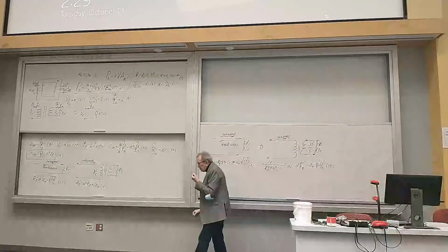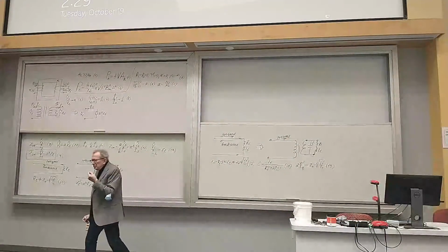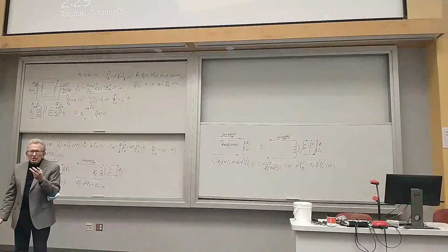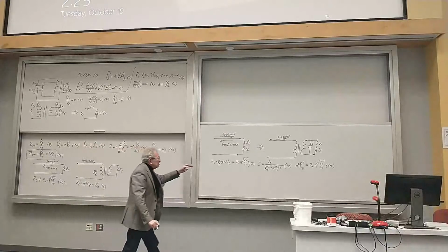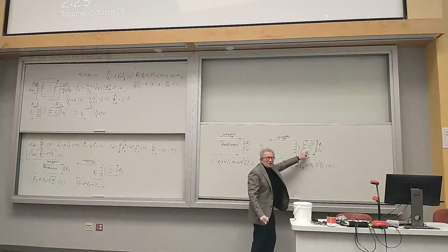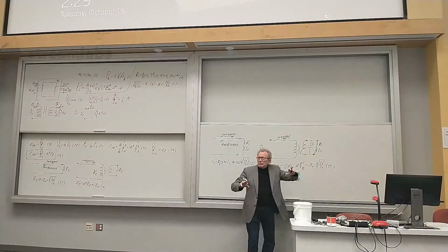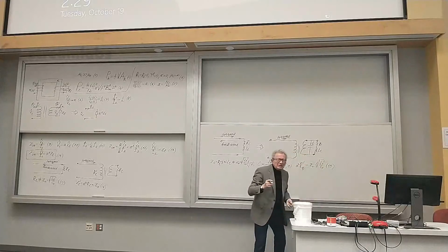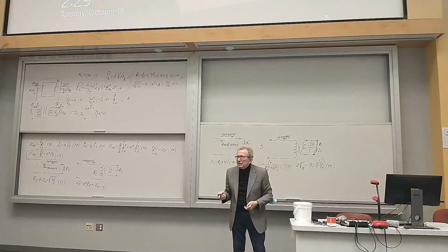You can see the capacitor is used again. The capacitor is very useful in power engineering. As I mentioned, sometimes the capacitor here will play another function. During the transient, when this capacitor is not charged, it's like a short circuit, and it will protect the load, because most of the high current will go through the capacitor.